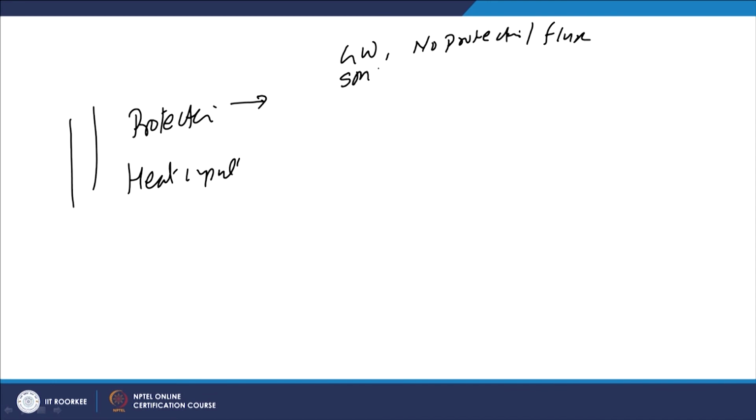In shielded metal arc welding, for protecting the molten metal, we use the inactive gas environment or envelope which is created due to the combustion of the coating, plus the slag cover which is formed. Protection is poor, but still this is the approach for protecting the molten metal from interaction with atmospheric gases.